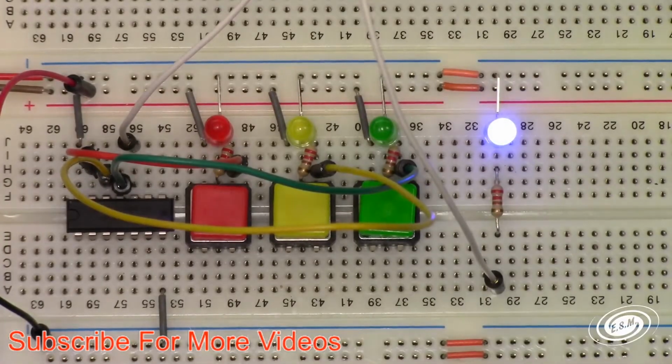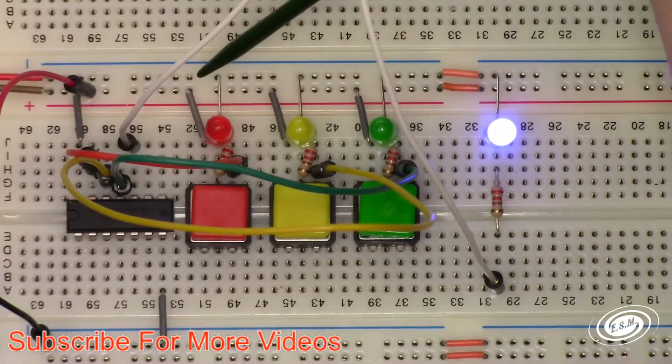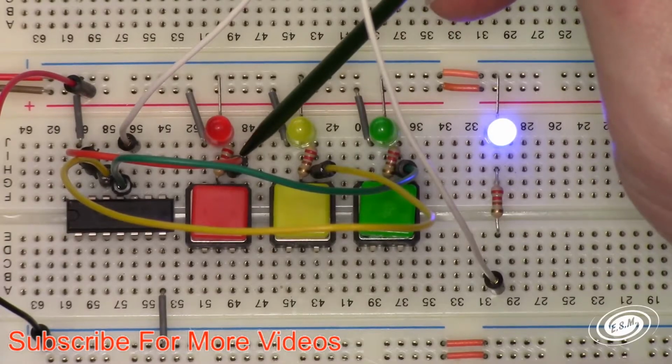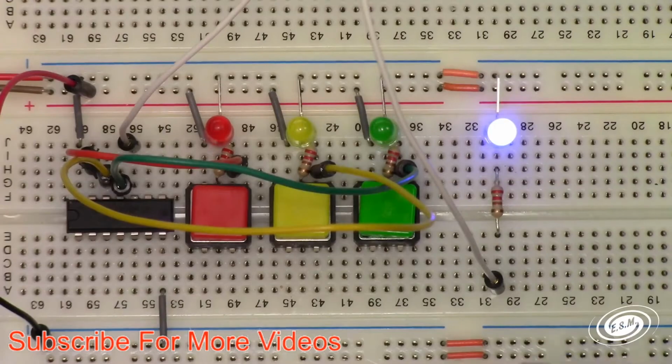Okay, that was my mistake. I want to know how many of you yelled at me that I had the inputs to the NOR gate hooked up wrong. I had them set to a high. So I had them coming off the power rail into the inputs instead of off the ground rail. So they're set to a 0 right now. So without the buttons pressed, they're at a 0, and all I was doing when I was pushing the buttons was lighting up the LEDs.